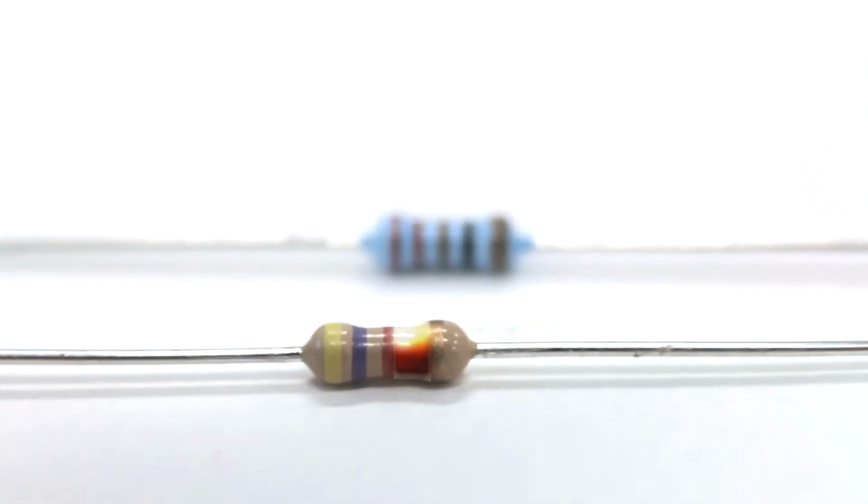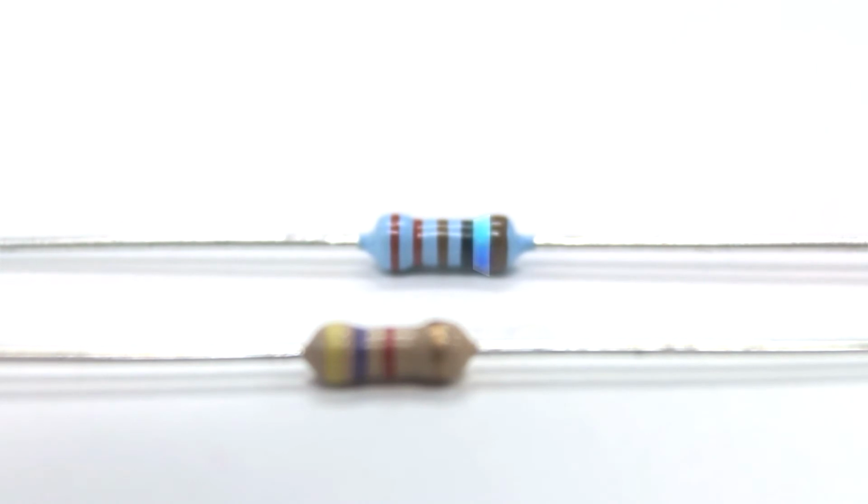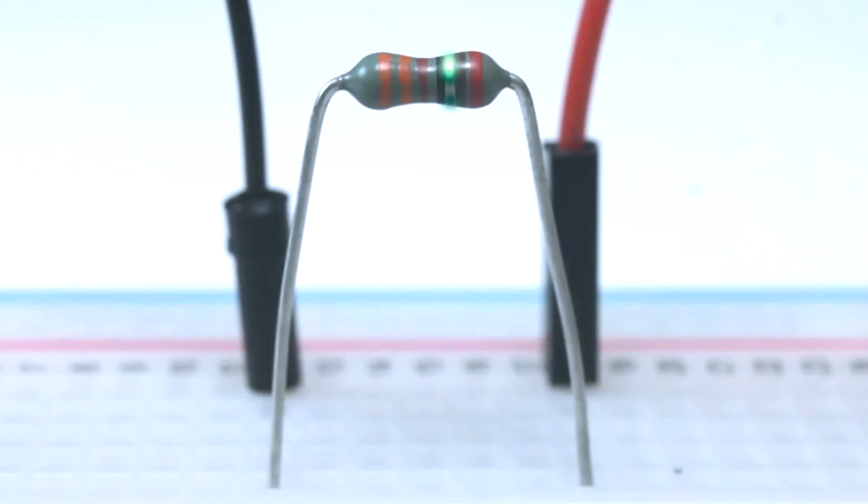First, rotate the resistor so the gap between the two of the bands is on the right side. In the case of a 6-band resistor, the gap is between the second and the third bands. Unfortunately, it's not always clear where the gap is located, especially on resistors manufactured overseas.